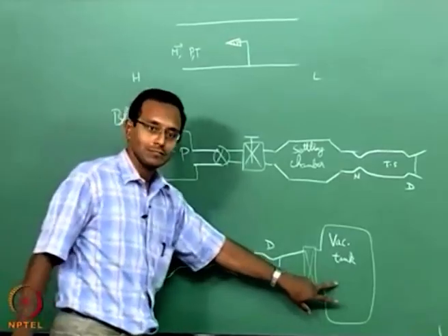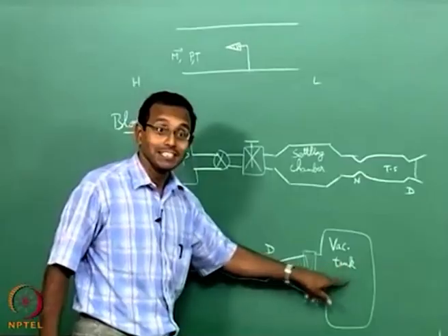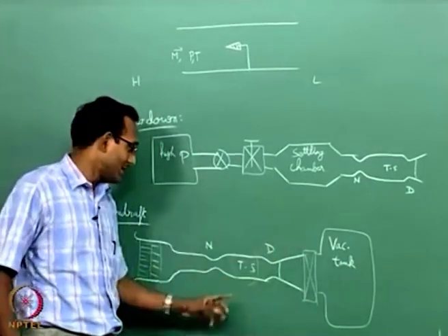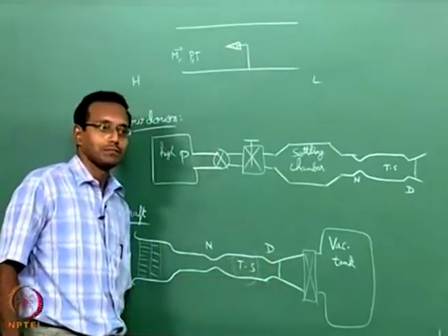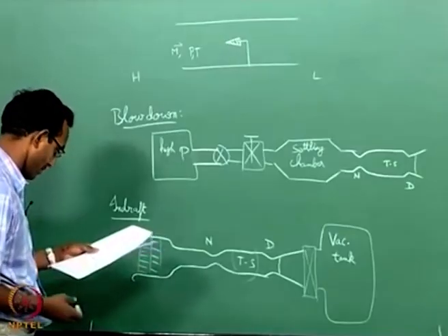Okay. Same thing goes here. When there is so much mass flow coming here, that is going to fill this tank, which is decreasing the pressure downstream. So, the delta P across is decreasing. So, eventually there will be a point where the shock moves more upstream, can happen that way, that is also a possibility. Okay.